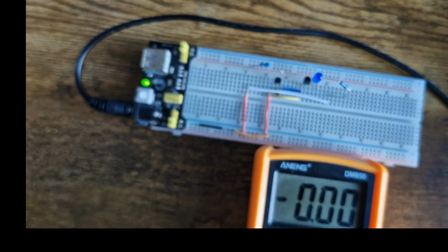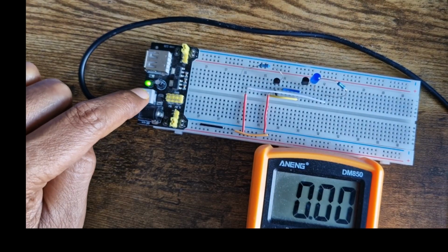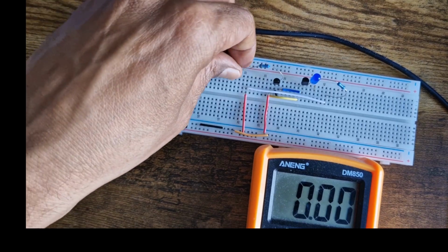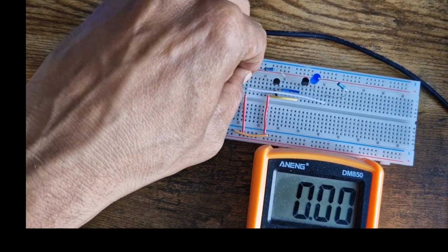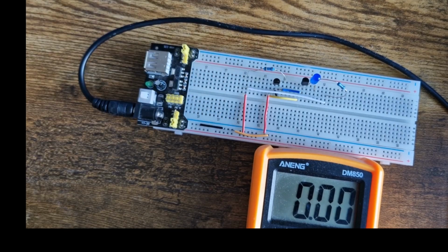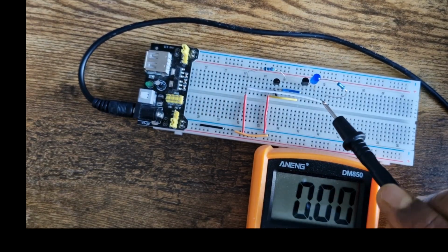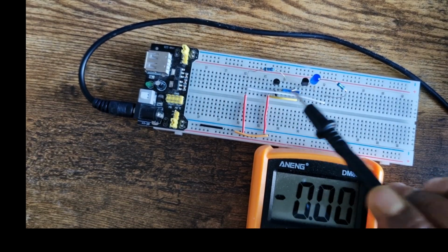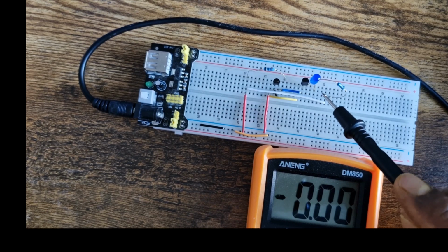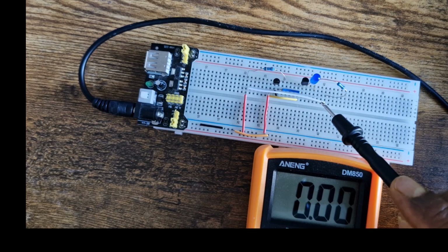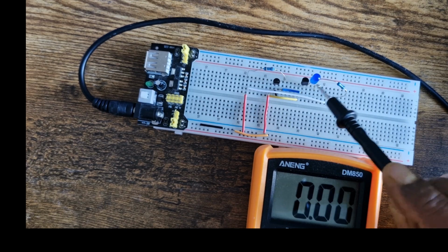So plus 2.15 milliampere is the current. Again I remove it, switch it off, and get the resistor back to its original pin. Now I have to measure the same current to see whether it is being mirrored into the right part of the circuit or not. To confirm that, I will now insert an ammeter in this part of the circuit.